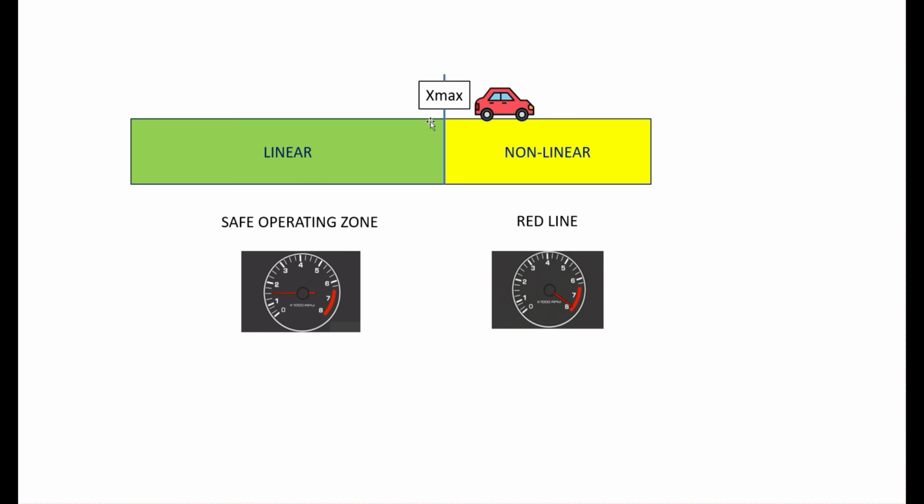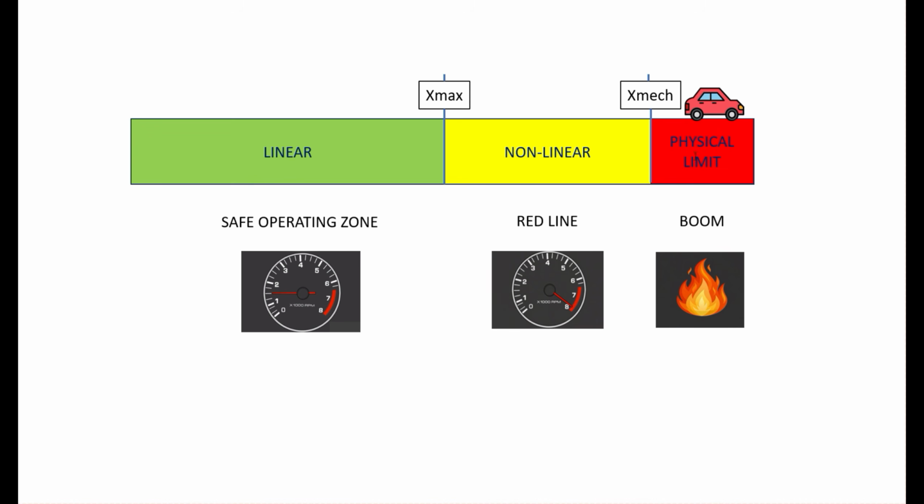So you can push it into the Xmax, but as I said, it's like driving your car in the red line zone, right? And then if you really start pushing it well into the Xmax area and beyond, then you're in the danger zone, and that's when speakers suddenly fail. So next we're going to move on and take a look at FS, or resonant frequency.